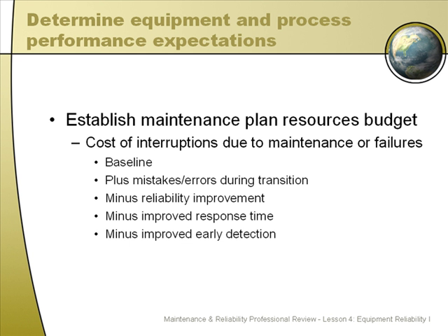The other thing is you need to take credit for some improved early detection. As you become more adept at doing good preventive maintenance and your predictive maintenance program comes into its own, it's going to start collecting enough information to avoid failures and predict them much earlier. So what will that do? Well, for one, you're going to be fixing less breakdowns, and you're going to be doing more minor repairs before the actual failure occurs. So when you have this early detection, it gives you time to plan, and when you do finally do the work, it's much simpler and easier work to do than you would have had if you ran to failure.